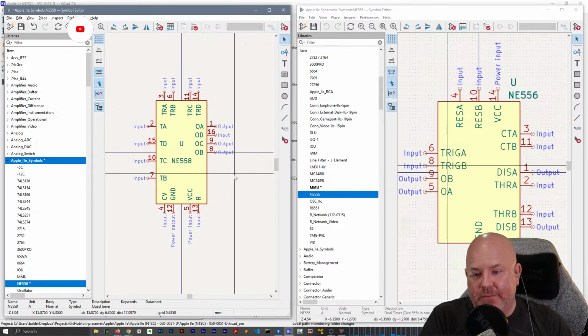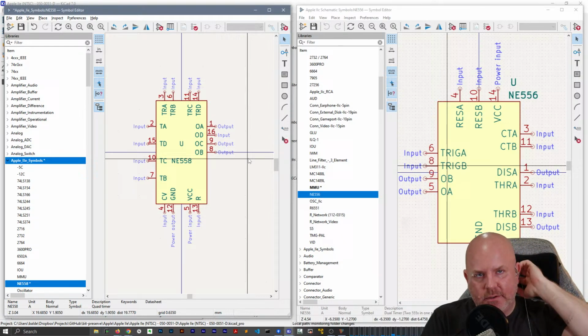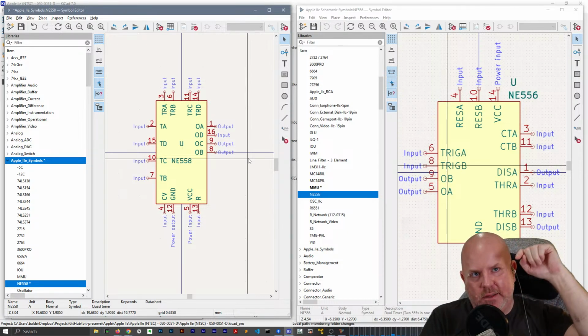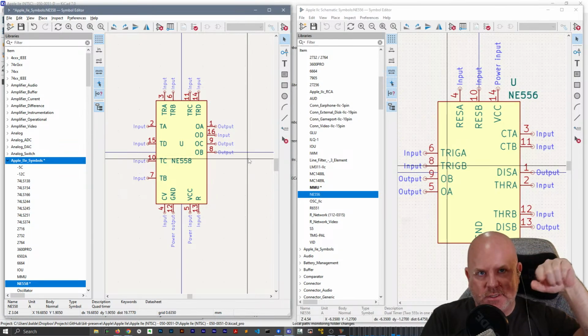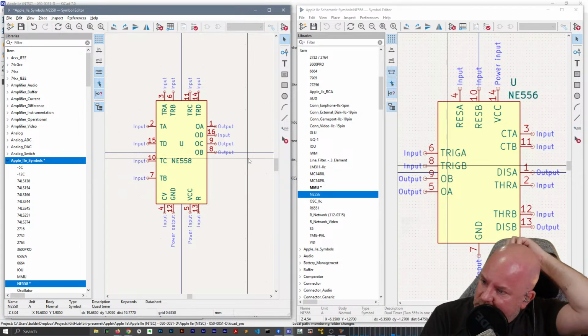Yeah, so the 558 anyway. What I was getting stuck on is that the 558 is used by the game port to tell the paddle where the paddles are at. Because you basically hit each of the timers, and then you see how long it takes for it to reset. So, oh, the 2C only. Okay, that's why.